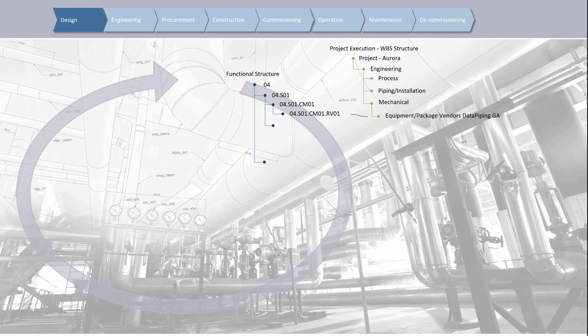The information from these disciplines are usually 2D process flow diagrams, PFDs, piping and instrumentation diagrams, or P&IDs for short, general arrangement drawings, ducting and instrumentation diagrams, material lists, etc. In addition, there is usually a more or less multidiscipline 3D plant model as well. All of this information needs to be consolidated and monitored against the project execution plan, or the WBS.